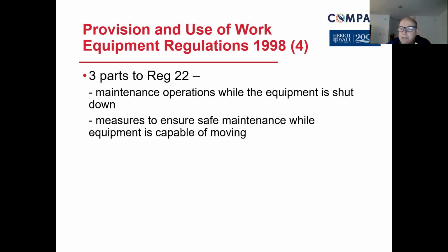If you think of it differently, if you have something like a switch that, when you lose power, has a mechanical link and it brings something in, so at the top of the press it stops, or you have another mechanical switch further down, or another one further down, but no matter where it is, the press stays at that position in a safe state until energy comes back in, the switch goes down, and so does the press in a controlled manner. So looking at it in terms of variations on what could go wrong.